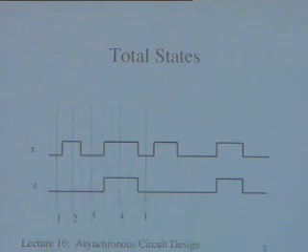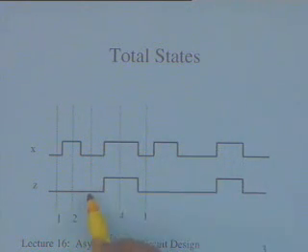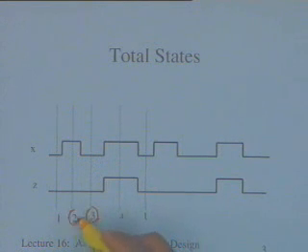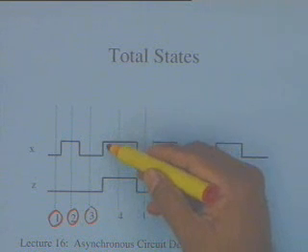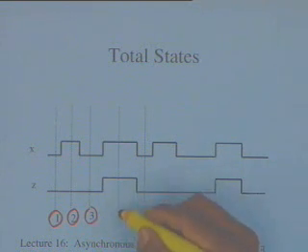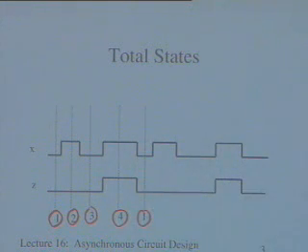Now we come to something very important here. So this is, of course, input 0, output also 0, but this needs to be distinguished from the previous state 1. The reason is that now the odd pulse has passed. So this is what is capturing the history of the input. Although the input is 0, we still have to have a separate stable state 3, and I cannot map this onto 1. And now finally, when the input again goes to 1, this particular 1 corresponds to the even pulse which needs to be passed. So I have another stable state 4 for this. And once this pulse passes, I will go back to 1 and repeat this process over and over again.